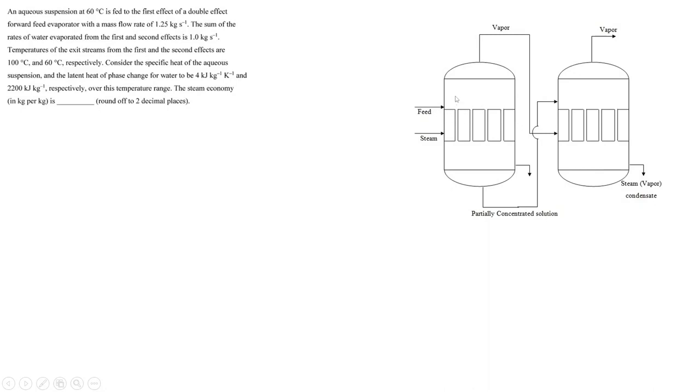In the first effect, the concentrated solution will be fed as an input to the second effect, and similarly the vapors generated in the first effect are used as a heating medium in the second effect. Practically, this steam and condensates are removed from the evaporator, but for our purpose, for energy and mass balance, we will be neglecting these two streams.